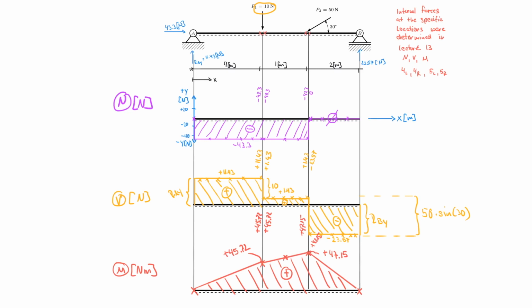So one important thing that we just discovered is that the shear force is really the derivative of the moment over x, right? So what we have done without noticing it is actually differential math, because if you take a look at this function, it's really the derivative of that. And that tells us one very, very, very important thing about the moment function, besides the ones that we already talked about.